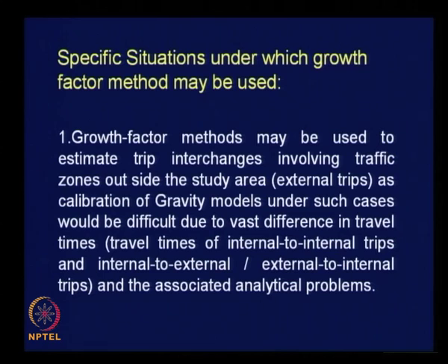Growth factor methods may be used to estimate trip interchanges involving traffic zones outside the study area, external trips, as calibration of gravity models under such cases would be difficult due to vast differences in travel times.